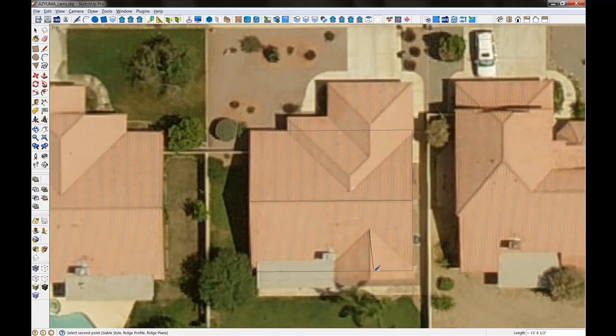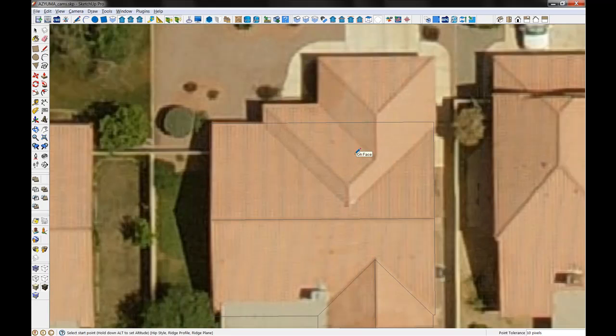We just digitize the ridge line. Inferencing tells us when our section is perpendicular to the previous section and also when the eaves match. And it's constructing the Boolean operation of those shapes now. And the next sections are hip roof, so we'll set the hip roof selection. And then again we just digitize the ridge line. Inferencing tells us when it's perpendicular and when the eaves match. And then finally we'll do this garage section here.